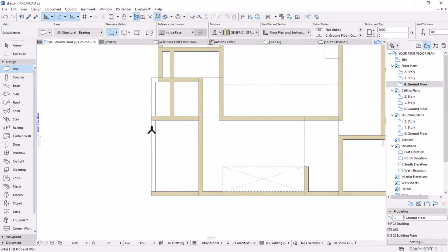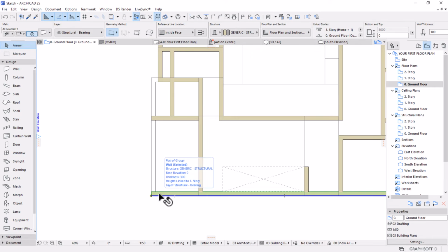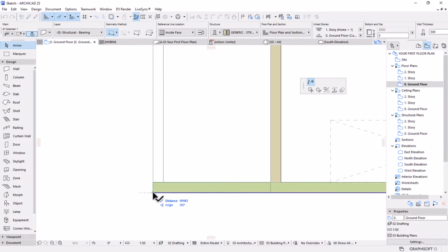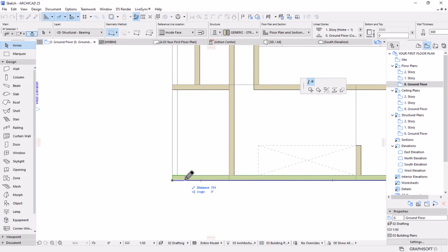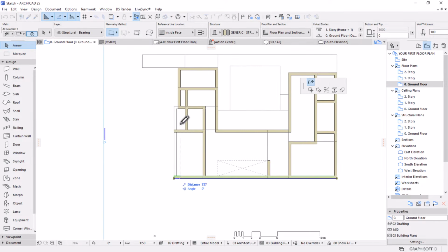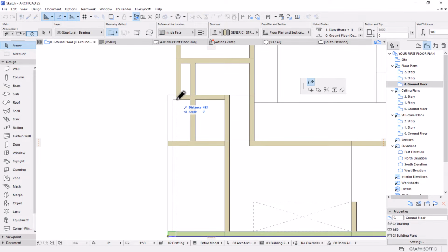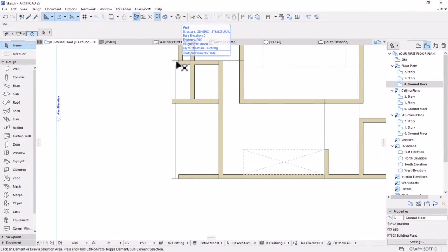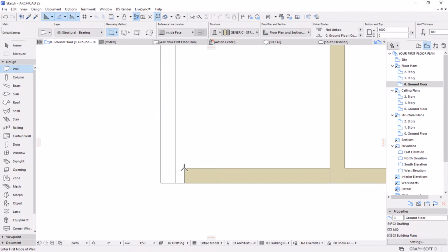Perfect. So we have the same situation here. We have to align this wall. Let's pick this wall and then pick the point of the wall like that. On the pet palette, it will give you the stretch command or stretch tool. So hold shift to restrict it horizontally or orthogonally, then reference with this line like that. And then I'm going to pick parameters of this wall again, then draw the wall there.